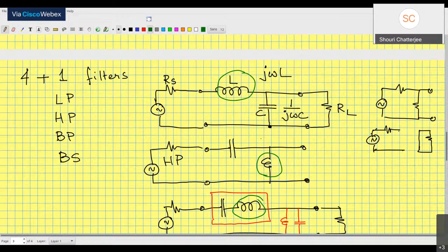The other way of doing it is through emulating the signal flow graph of these circuits. In these circuits, you can come up with the transfer function, polynomial by polynomial, with the help of a signal flow graph. You would have learned all of this somewhere else, in control theory for example. So you can build the same signal flow graph with the help of op amps.